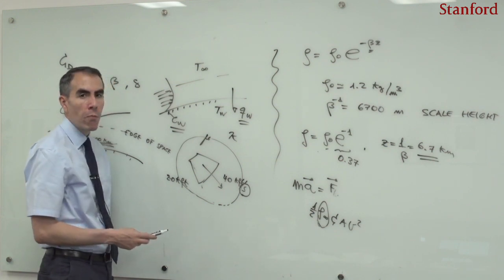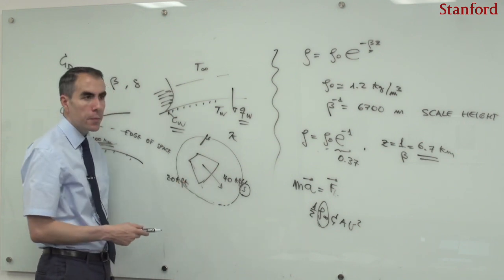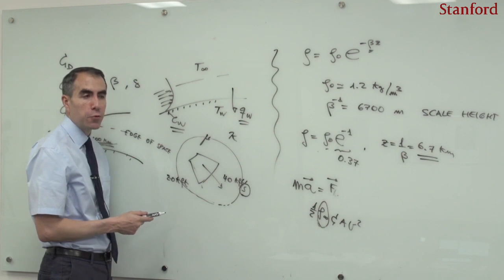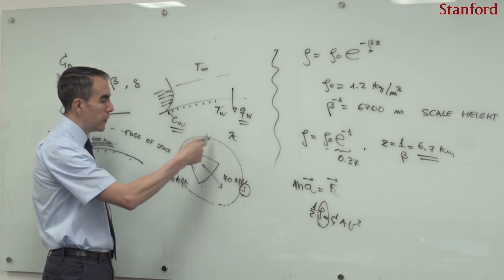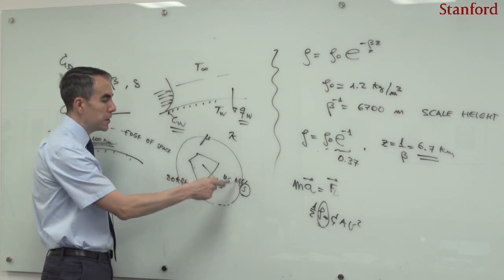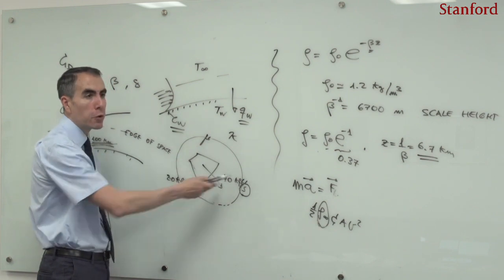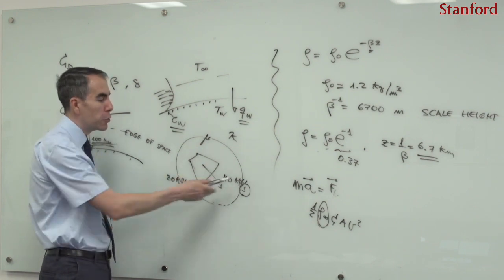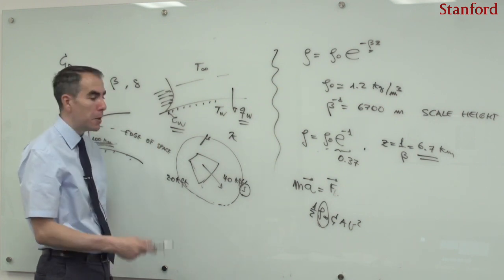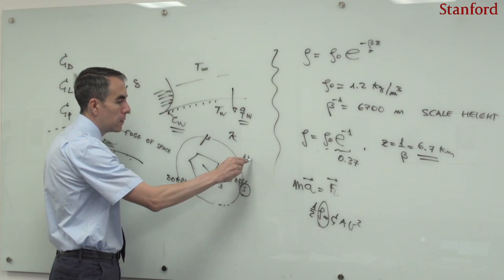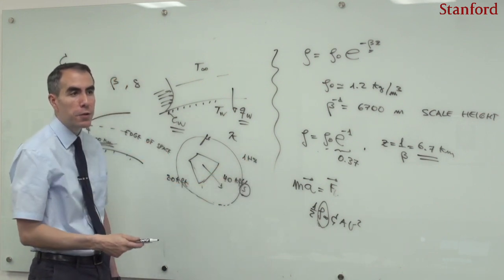So just trying to give you some idea, if you had to calculate the numerical simulation subject to those variations, you would take the capsule, and then around the spacecraft, the density will have to vary by 20% in just 1 second, right? So the boundary conditions would actually change. And those boundary conditions will be changing correspondingly to that peak with a frequency of about 1 Hz. That's, for instance, the widest peak that you have seen here. If we go back to the screen.